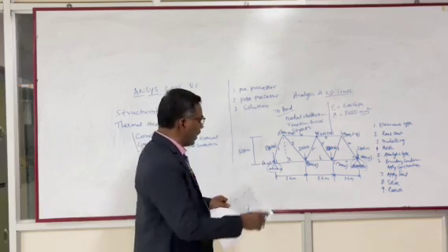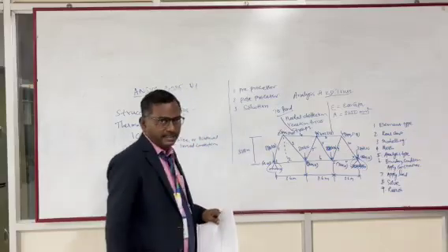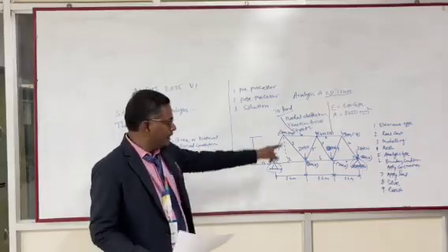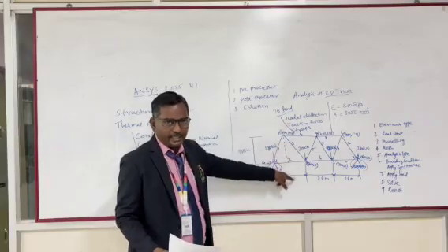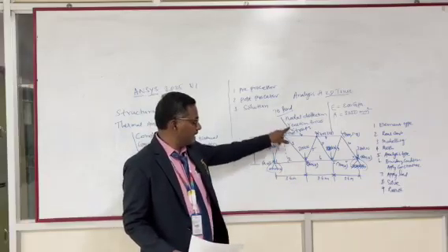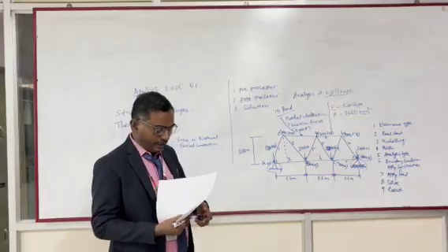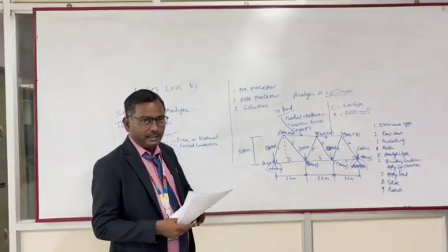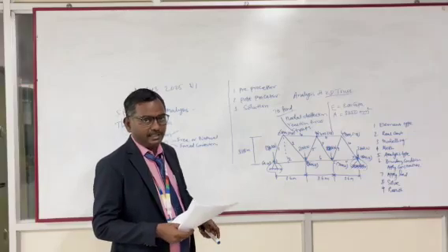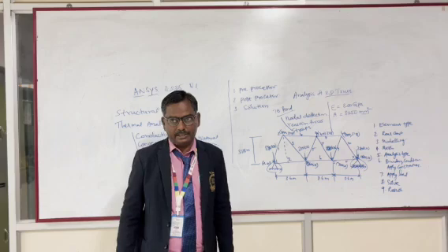We are going to take all these values. So these nodal deflection and the reaction forces and stresses in the result column. So directly it is given the nodal deflection in the y direction, not in the x direction, y direction, and the reaction forces and stresses. After that, we can solve the same problem manually, and we can compare the result, manual result and the Ansys result. Okay, so this is the final steps in using Ansys.